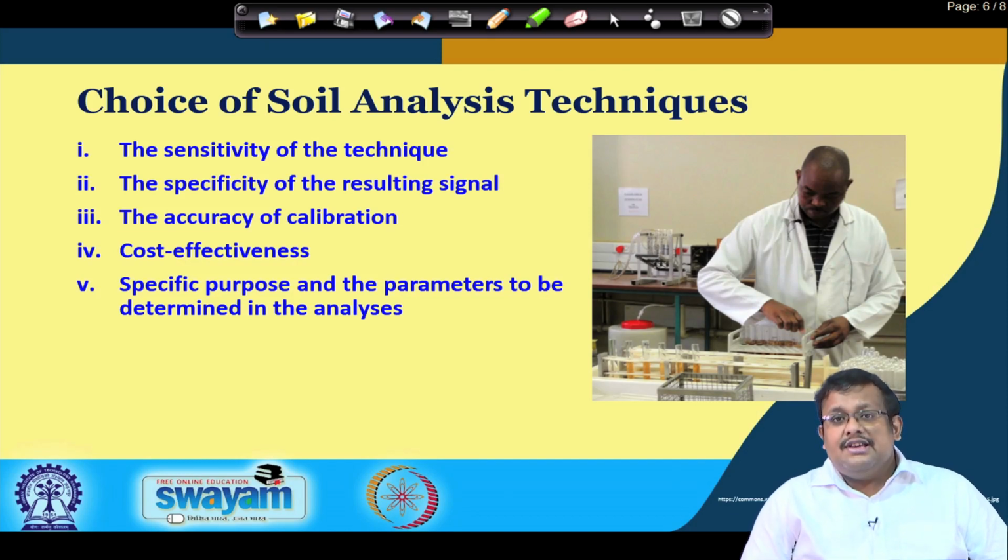For every analysis, you have to calibrate the instruments using the prescribed steps. Most of the instruments require calibration before their run, and most require everyday calibration. Some instruments require calibration after certain samples. So, the frequency varies from one instrument and one technique to another. However, calibration is universally required for all the instruments which we are basically using for measuring different inorganic and organic pollutants.